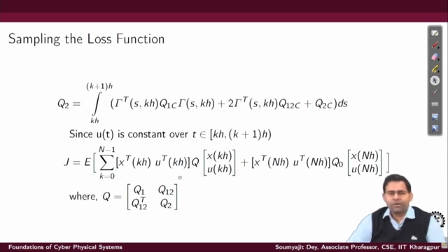Okay. So, you have the loss function designed here, and you have this state space formulation, where with x and u, you have a quadratic form over which you have a summation, and you also have the final state n for which you have this. Note that this summation is only over the first term, and at the end you add one term for the final values of x and u at the nth step horizon. Okay. So, this is your final J.